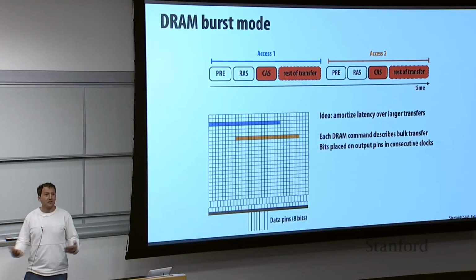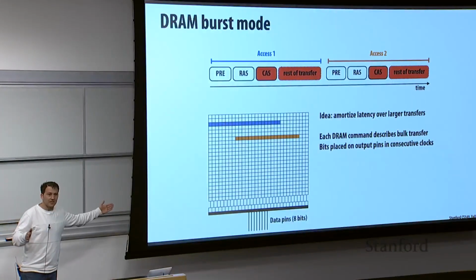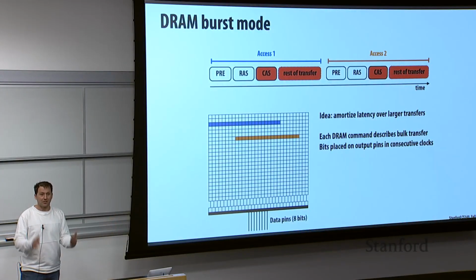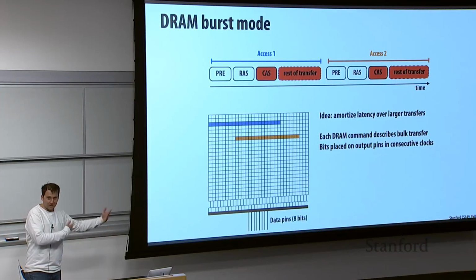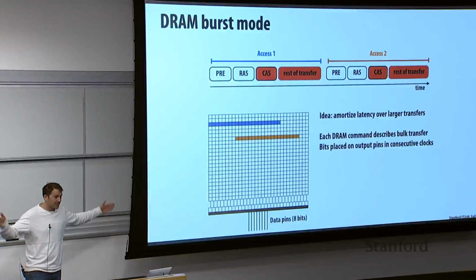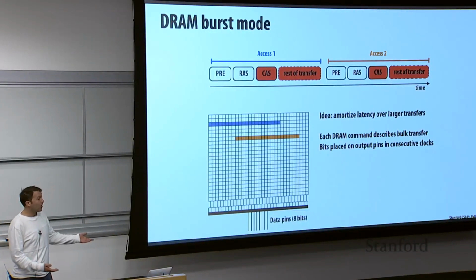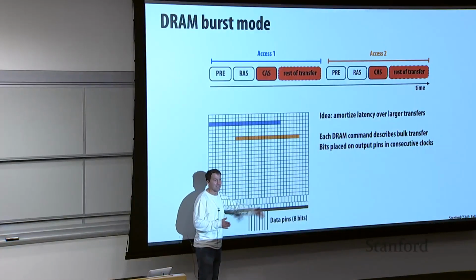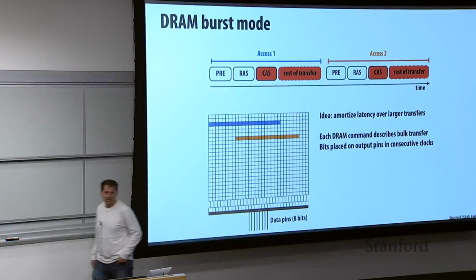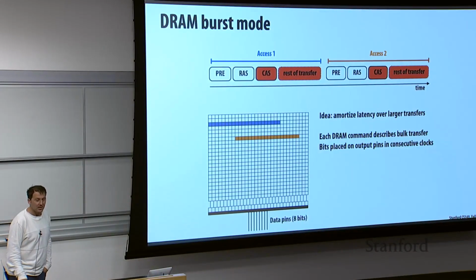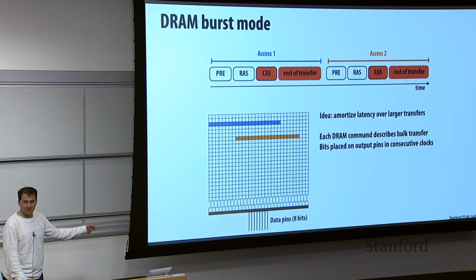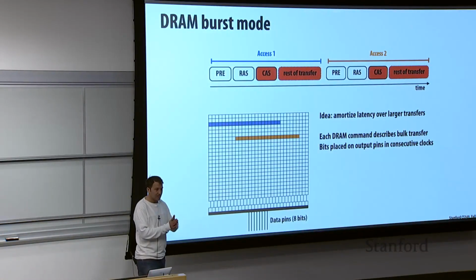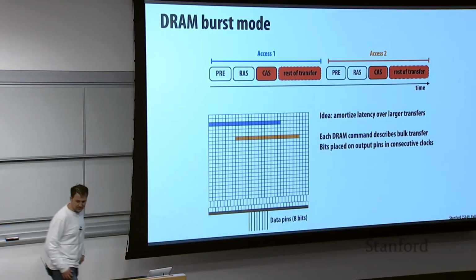That works if your access pattern affords big contiguous data. By the way, there's a reason why if you run right through your memory system, you get the best performance, and it's not just that you're using the whole cache line. It's that the memory controller can communicate with the DRAM system in the most efficient way possible if it knows the access pattern is all contiguous. That's also the reason why there are cache lines. Cache lines are 64 bytes, which suggests big bulk contiguous transfers are more efficient, right? A memory bus is 64 bits on modern Intel stuff. A modern cache line is 64 bytes, 8 times larger, which means there's a lot of bulk transfer there.